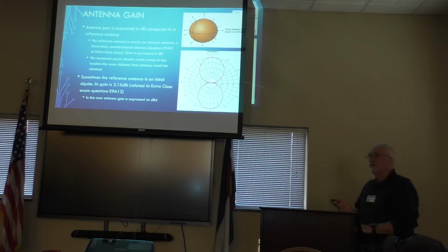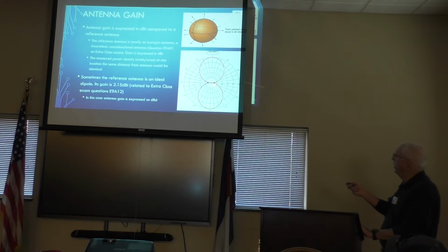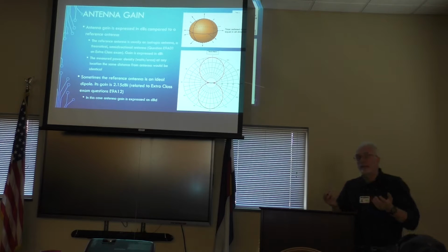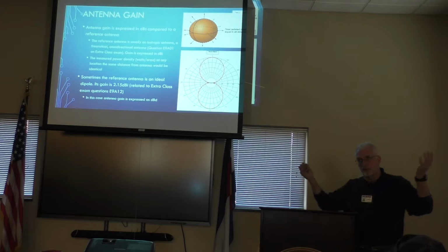But of course, people will do things to throw you. Sometimes that antenna gain is represented in dBd. dBd is in reference to an idealized half-wave dipole antenna, where here's the antenna in the middle, and the propagation pattern goes out broadside to it. So the maximum propagation off of a dipole is going to be, if this is east-west, it will be north-south. Again, ideal dipoles, it's going to depend on how high it is, how many wavelengths above the ground, to get certain reflections off the ground.